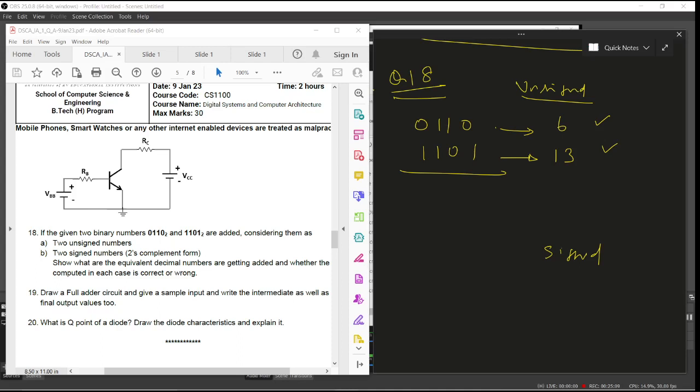But what is the result going to be? It's a simple addition. It is going to do the same full adder addition. So let us do the addition here. 1, with a 0 carry here, 1, and then a 0 carry. Now this is going to be 0, and it is going to give us a carry of 1, which is again going to be a 0. Then there is a carry coming out here. Now, as I have explained in the class, in the unsigned case, the carry coming out of this addition indicates that it has overflowed.